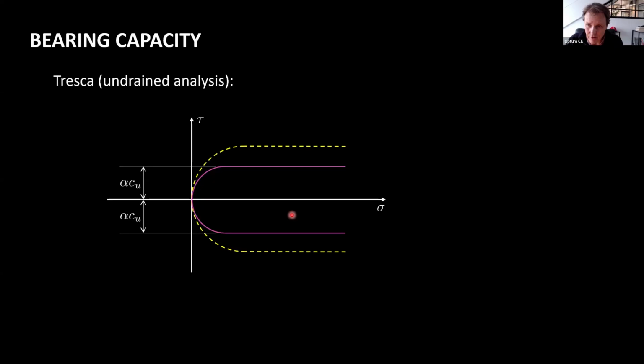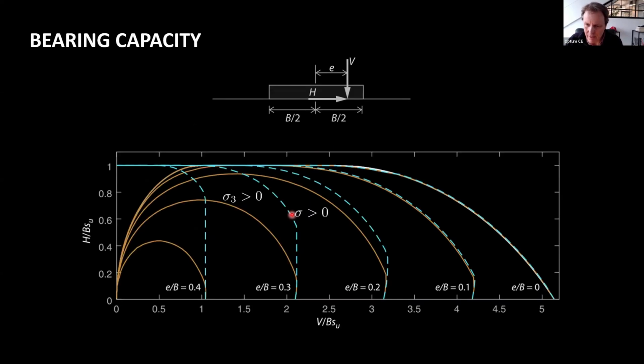That's the way tension cutoff is implemented in GX, and I believe this is what is meant by a tension cutoff. There can be no tension in the interface, neither at 0 degrees or at 45 degrees or at any other angle. So that's how that is.